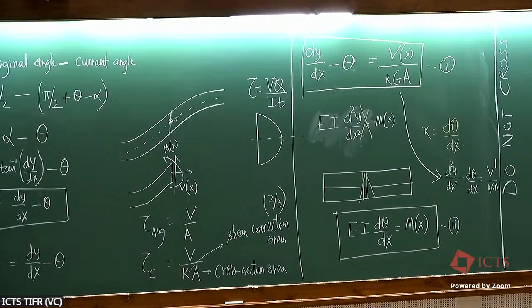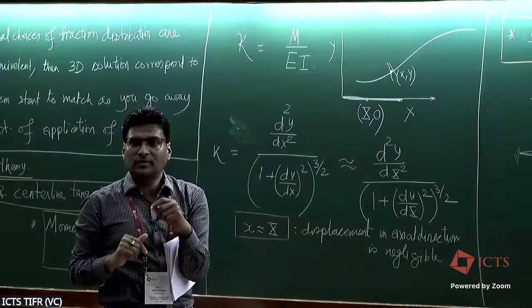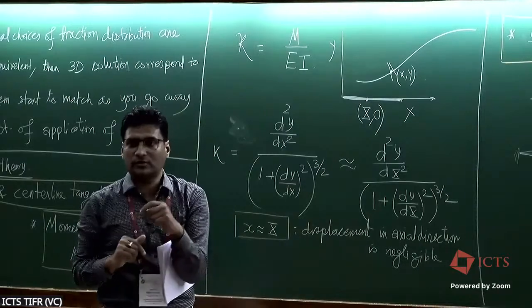The pulling or pushing of cross sections here will not come through what the center line is doing here. It has to come through what's happening to the orientation of the cross section. Are they changing along x, or are they not changing? Only then will they either push or pull each other on two sides of the center line. Yeah, that's a very good question.